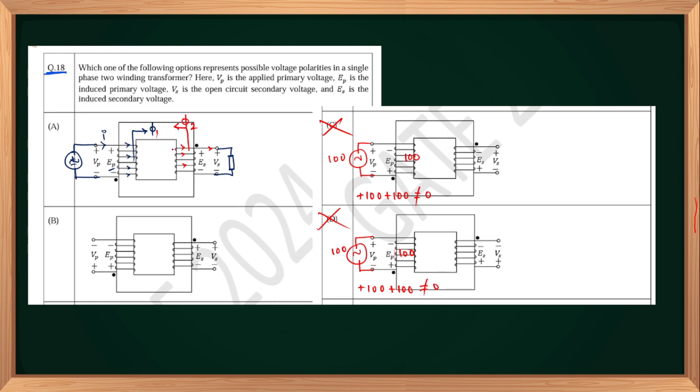So this coupling is a magnetic coupling, which is negative coupling. This is negative magnetic coupling. Transformer is a negative magnetic coupled circuit. It is not positive coupling, not additive coupling. This is subtraction. The flux produced in the secondary is going to oppose the flux produced in the primary. The MMF produced at the secondary must be compensated by the MMF produced at the primary. So MMF balance has to happen. They should not add, they should oppose. So negative coupled circuit. Transformer is a negative coupled circuit. So A is satisfied.